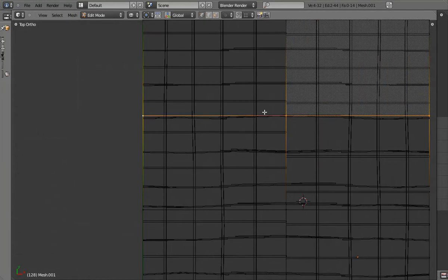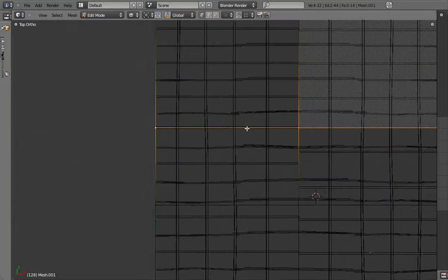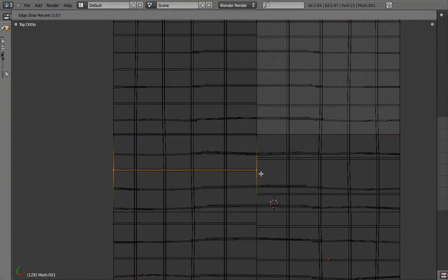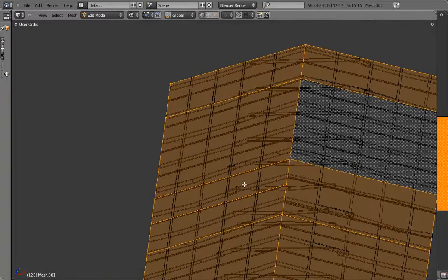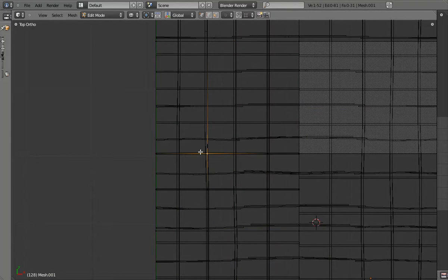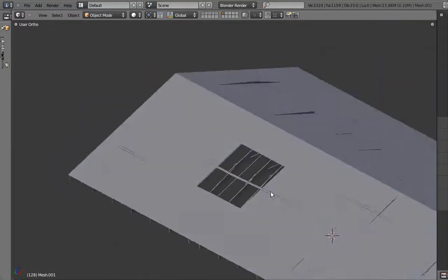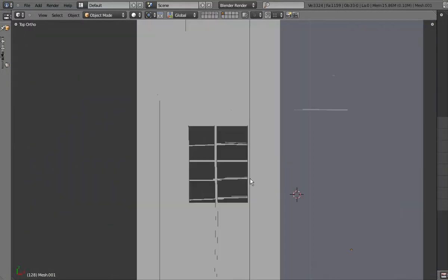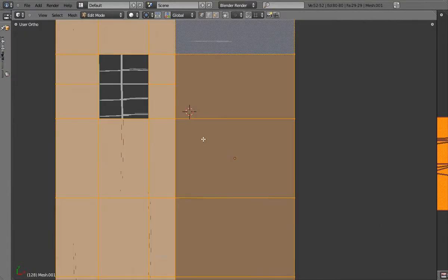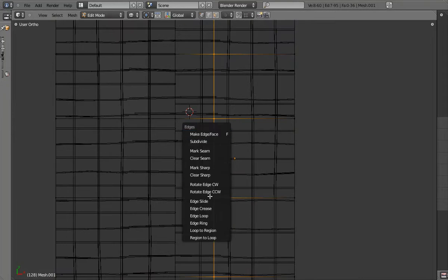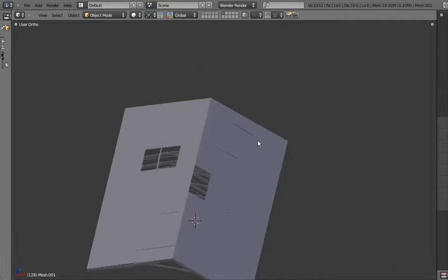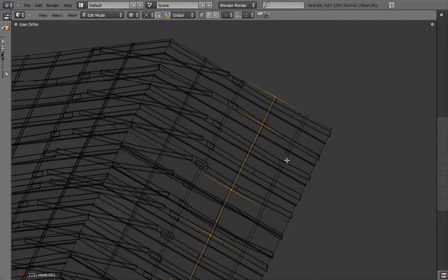And I'm going to line the loops of vertices in the roof with the trusses. That's how I'm going to create nicely aligned holes in the roof between each of the trusses. Between the trusses and slats, I should say. I added a loop cut there by pressing the Control and R key and then sliding the edge up towards the top.